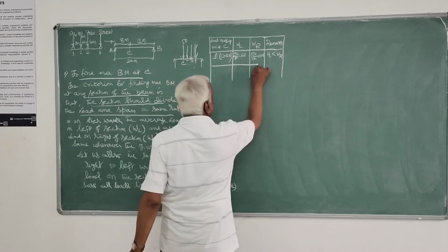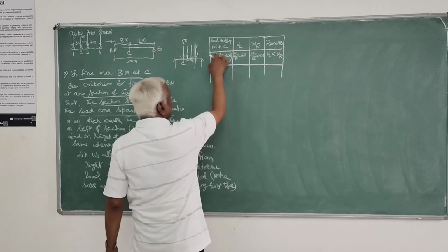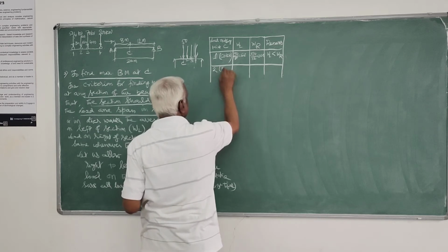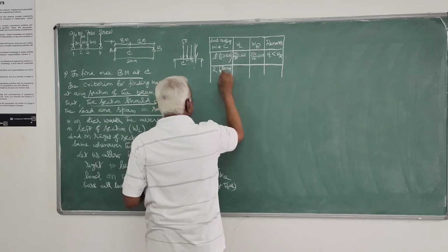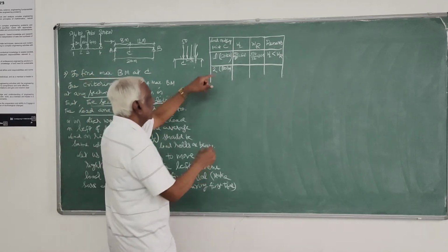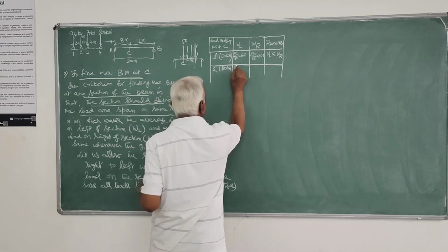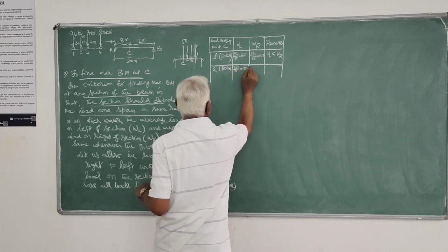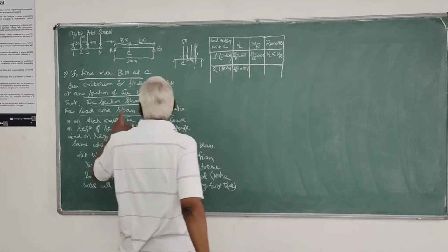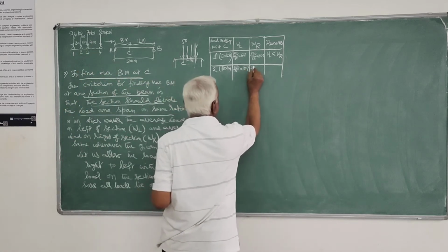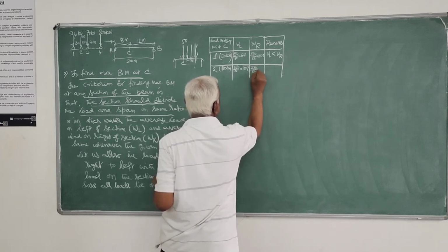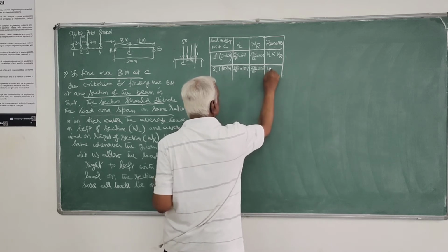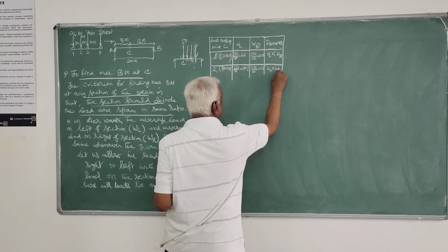So this criterion you are satisfying in the form of a table calculation like this. Then to consider the second load crossing point C, that is 100 kilonewtons, that 100 has to be considered on the next line. So here on the left side WL will be 150 divided by 8, that is 18.7. On the right side, it will be 270 divided by 12, that is 22.5. So again, WL is less than WR.